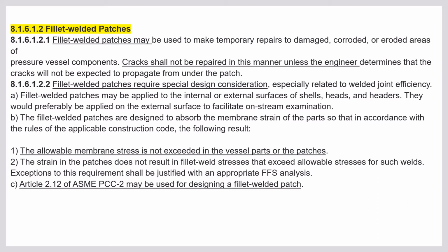So fillet welded patch. If there is a defect and we want to put a patch plate, okay, patch plate. If there is a repair and a patch plate is required and the patch plate is a fillet welded patch plate, then what is the requirement? Fillet welded patch may be used to make temporary repair to damaged, corroded or eroded areas. Okay, if there is a damaged area, corroded or eroded, corrosion by normal process, erosion with some mechanical pressure.